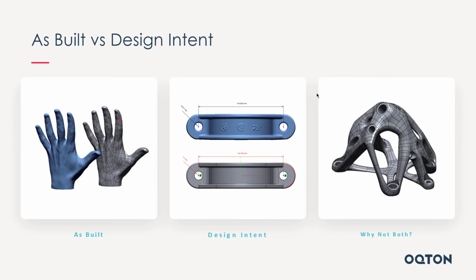The second option here is, with a mechanical part, if I 3D scan the shape and I measure between those holes, let's pretend the distance between those holes is supposed to be 3 inches. If you scan a part or measure with a CMM or a pair of calipers or anything, you can grab those calipers and make a measurement from hole to hole. It'll never be 3 inches, right? Because there are tolerances built into manufacturing. There's error at every step. It may be very small amounts of error. The devices that we build today are very accurate, but it will almost never be 3 inches. If it is, then you need to play the lottery.